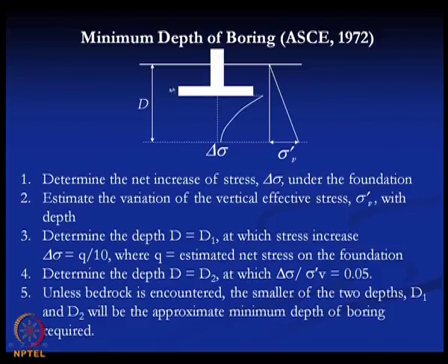Suppose this is a foundation and D is the depth of the borehole from the ground. First, determine the net increase of stress under the foundation, that is, the increment of stress due to the applied load at the foundation level.